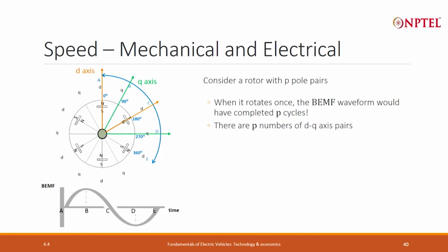and it looks funny because the d and q axis are not at 90 degrees, they are at 90 divided by p degrees. In this case, because p is 3 pole pairs, the angle between the d and q axis is 30 degrees. So, when I complete one mechanical revolution, I am cutting across 3 pairs of dq axis, and every dq axis is one electrically complete revolution.